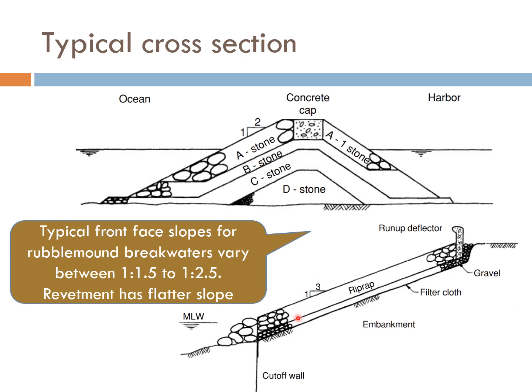For rubble mound structure used as a revetment, the design is also similar. A cut-off wall may be provided at the toe in order to provide anchoring and thus stability to the sloping riprap or armor unit. A wave run-up deflector may also be provided in order to prevent wave overtopping or run up to the land side of the structure.